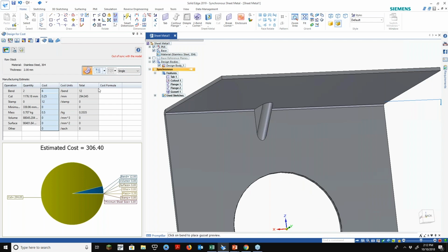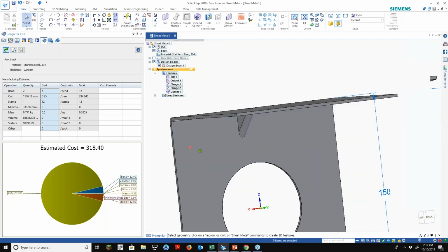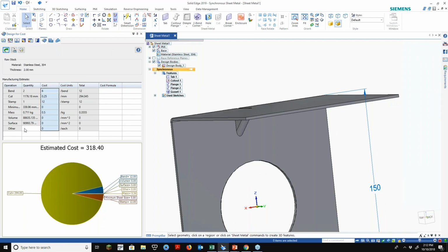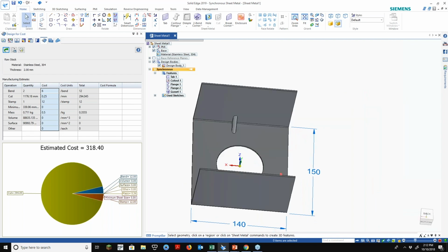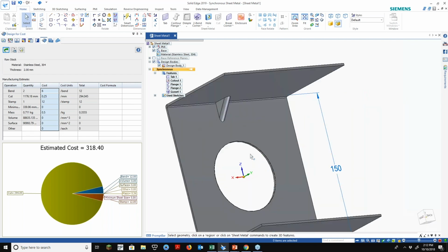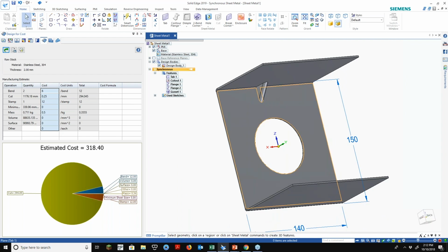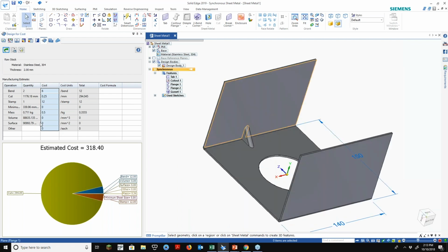So for features like that, you can specify certain features that do certain things. You can add holes. Right now, holes are just considered part of the cut. So if you're laser cutting or water jetting, whether it's a hole or not doesn't really matter. It's just another feature you have to add. But if you wanted to split that out for cost justification, maybe you do a post-machining process, you can add that in there as your own features.